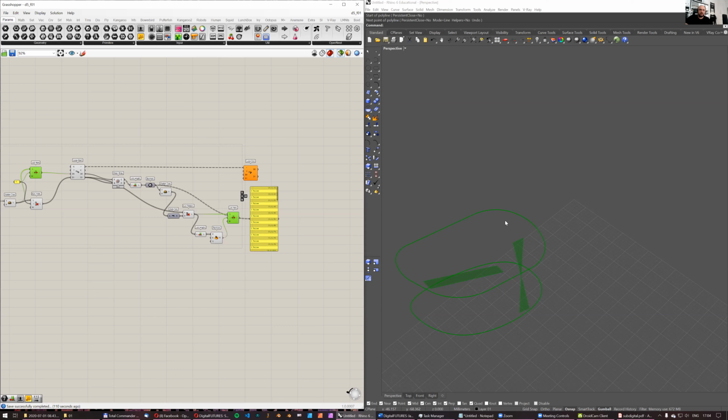And if the overall distance here and the overall distance here is the largest of all the selected versions of the table, then it's probably the best solution, because it means that the distribution of the legs is the most even one, like it's distributed all over the table the best. So I will pick that solution, which will be the best, the stiffest solution for that table.